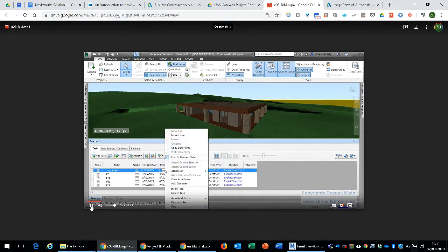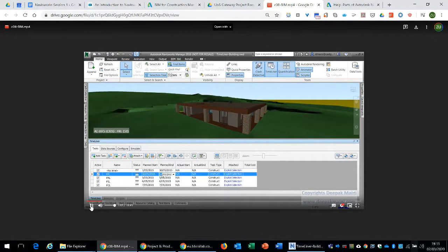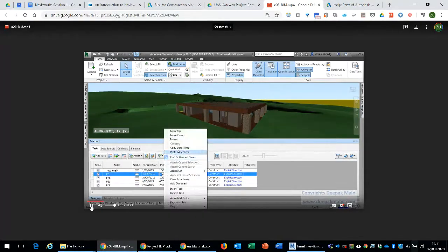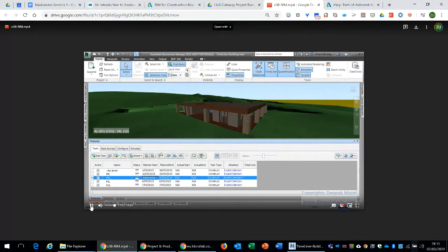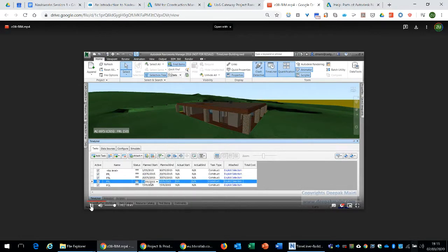So we could do it manually, and then we can copy the early finish of the previous task and then make it the early start of the subsequent task by copying and pasting feature. Right, now one thing to note here is this is not a scheduling software, so it will not be telling you what is the critical path or so. So this information and optimization of the schedule needs to be done in an external scheduling software like Microsoft Project or Asta Project, and here you will just bring the task.